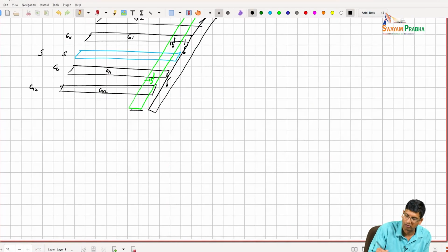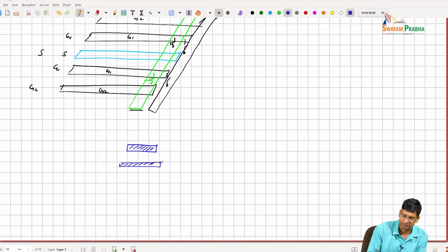Let's actually draw, maybe I'll translate this view to the vertical view. So this is their central signal trace. Below the central signal trace, they have capacitive strips, and this capacitive strip is shorted to ground. This is what they call the S switch, and this is what I called G1. And that switch over here is connected closely to the L switches.